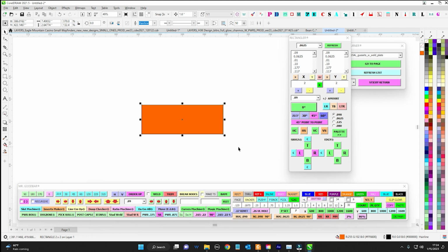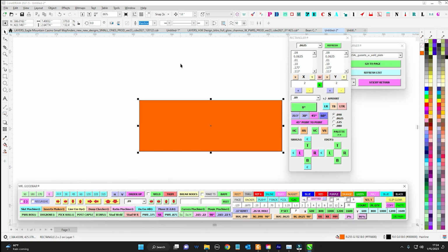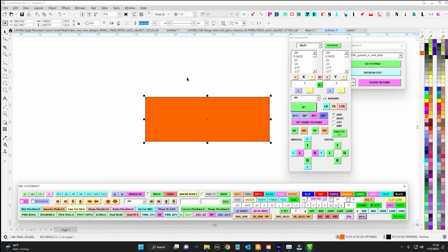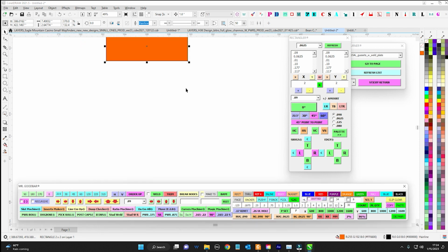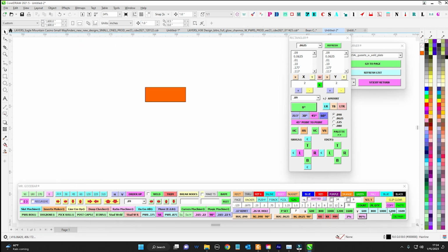A lot of times I'll take a tool. If there's a bolt that's going to be hindered, to see if a socket wrench will fit in there, I can make it 86% and literally hold the ratchet up with the socket on there and see, yeah, they should be able to get in there. It's going to be tight, but it's fine. Otherwise, I can make adjustments. But as long as it fits on my screen, that's why the 86% is there.